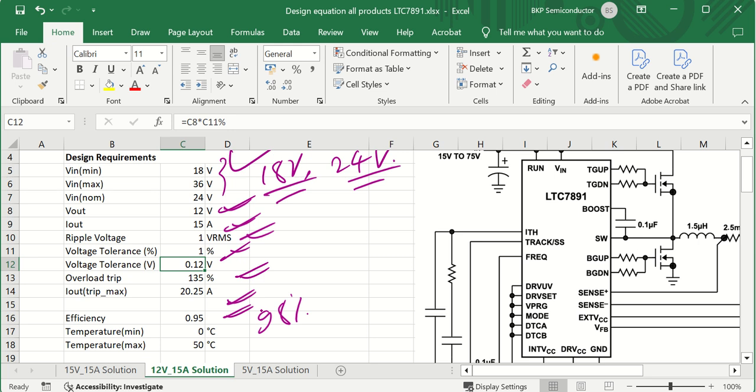And the temperature range of working of this particular DC-DC converter module will be 0 to 50 degrees centigrade. One more thing, this particular DC-DC converter can be designed in a form factor of, let us say, 100 mm to 50 mm, or even less than that. If you have space constraints, you can do that, or if you wish to have a little bit bigger size, that is always also good.